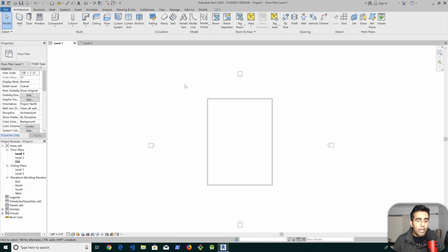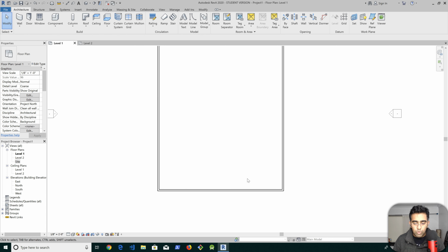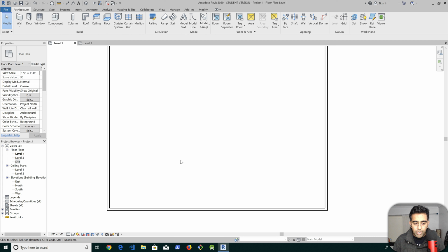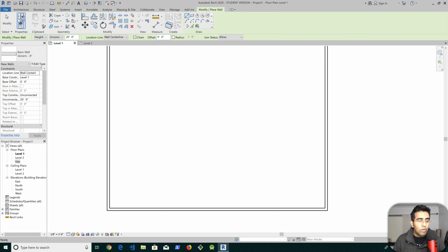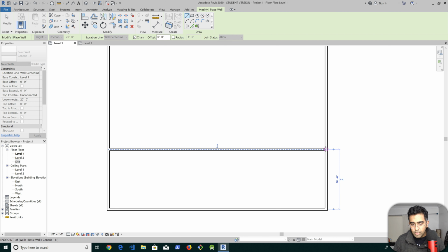Okay. Now, for example, you want to draw a line here. So we're gonna zoom in a bit, and I'm gonna leave some space at the front for a garage and for a lawn. So we'll click on the wall. I'm going to click here and then move straight up. Click again, press escape, and then you get out. So here we have this lawn area. Now we don't know what exactly the dimension is, right?